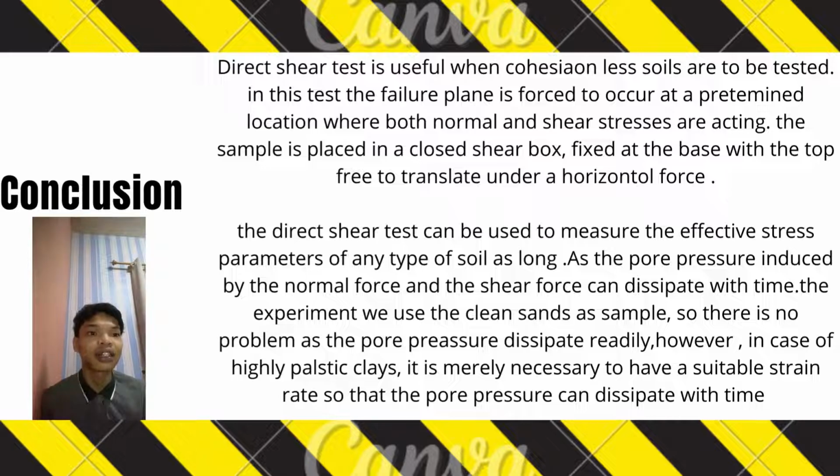The direct shear test can be used to measure the effective stress parameters of any type of soil as long as the pore pressure induced by normal force and the shear force can dissipate with time. In the experiment, we used clean sand as the sample, so there is no problem as the pore pressure dissipates readily. However, in the case of highly plastic clays, it is necessary to have a suitable strain rate so that the pore pressure can dissipate with time.